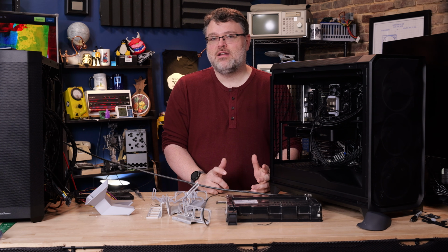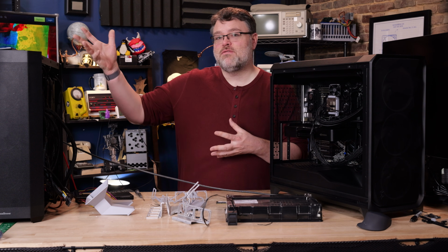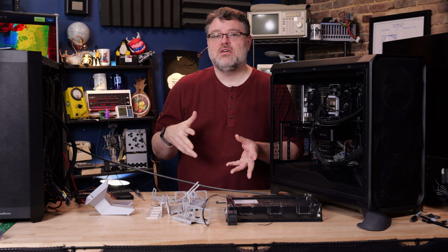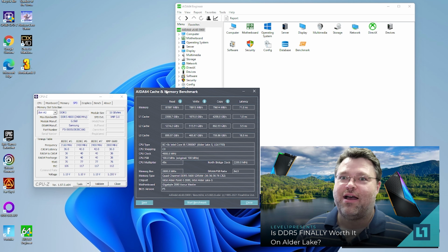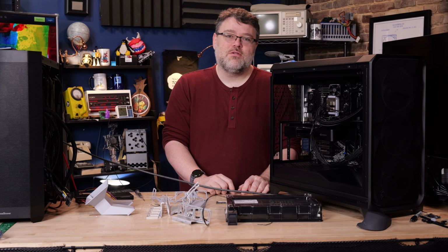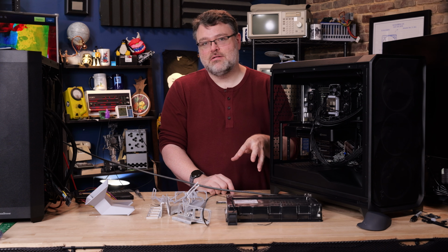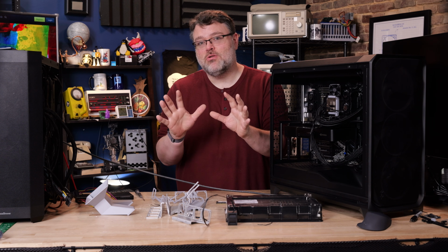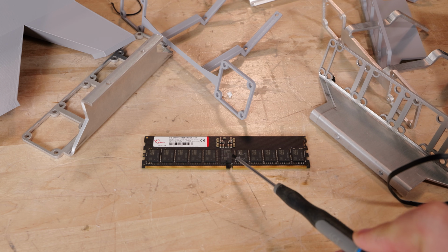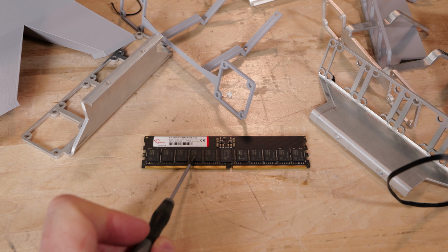The server team's priority is not affordability, and the desktop team is also cobbling together features cherry-picked maybe from future JEDEC specifications for more speed or overclocking or voltage, and it kind of turns into a mess. See also desktop DDR5 teething issues if you were following along there. Now you know why. But for this video, I want your takeaway to be the understanding that desktop use cases are barely a blip in the design considerations for the team that's working on server class and the JEDEC standard. That's part of the story of how we got here. If we take a closer look at our G.Skill 64 gig registered DIMM that I recently reviewed here, DDR5 is still a 64-bit interface.